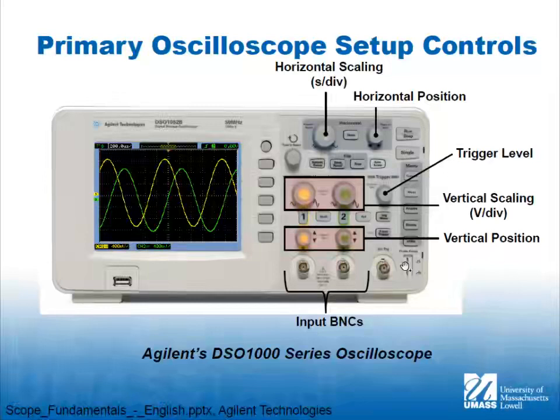And really what I want to get across is the horizontal and vertical axis, where the vertical axis is measuring the voltage and it's quantizing it into a digital number. Our digital number for actual digital signals is a 1 or a 0. It's a single bit because we're looking at it to be above or below a threshold. An oscilloscope is a quantized analog signal. So it might have 256 or 4096, some number of steps based on the number of bits. So if it has 8 bits, it's 2 to the 8th steps.